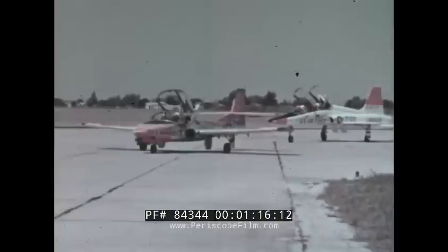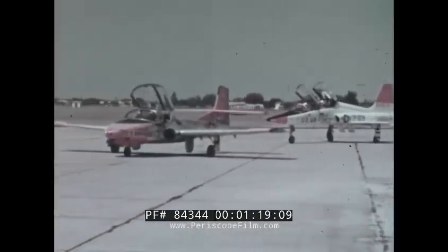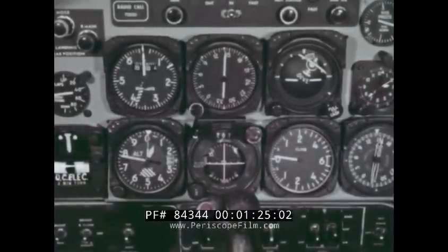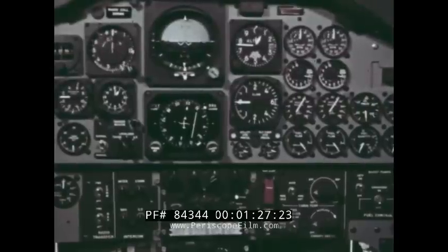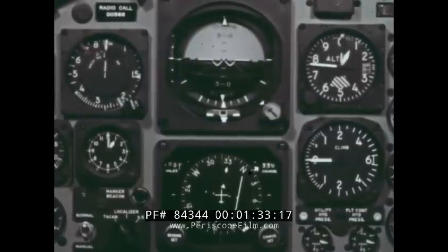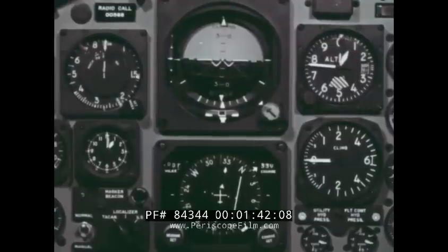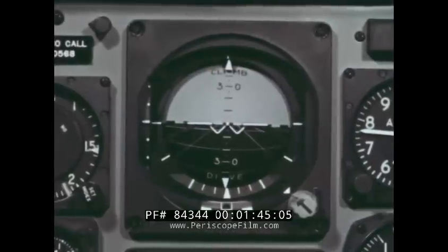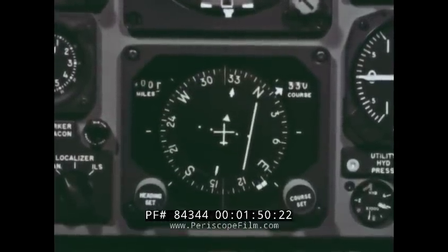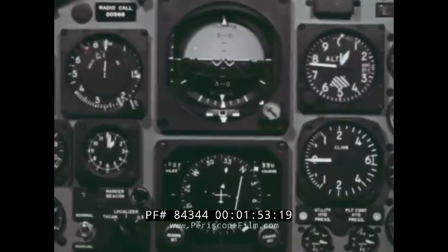Before we go into the operation and control of the T-38A flight director system, let us compare the conventional instrument panel of the T-37, which most of you have flown, with that of the improved instrument panel of the T-38. On closer examination, you will note that the major innovation in the T-38 panel is that package known as the flight director system, which contains two newly developed flight instruments: the Attitude Director Indicator, ADI, and the Horizontal Situation Indicator, HSI.